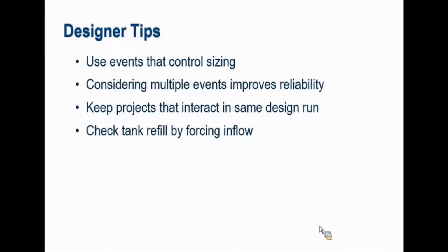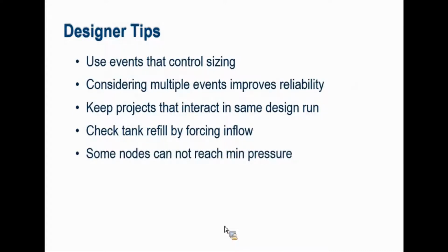You may have to check the tank refill by forcing some inflow, because maybe the controls might not be where you wanted them to be for the worst case scenario. Some nodes you'll find cannot reach the minimum pressure, or will always be at some low pressure, and that again could be a pump suction node or something like that. So you can not include those in the design study.